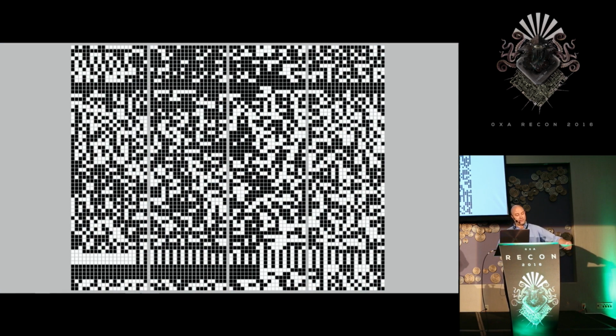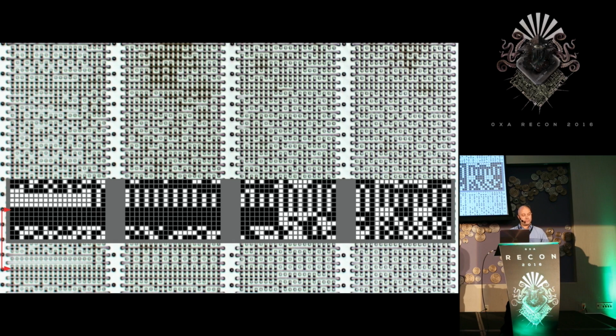After extracting the bits from the photograph, now I have a binary version of the ROM data. This is a visual representation of the bits that were extracted from ROM. The black boxes are 1 bits, the white boxes are 0 bits. In this image, I overlaid the extracted bottom 13 rows of bits over the photograph. You can see some visual patterns within the bits, and this is a really good indication that the ROM is probably not encrypted or heavily scrambled.